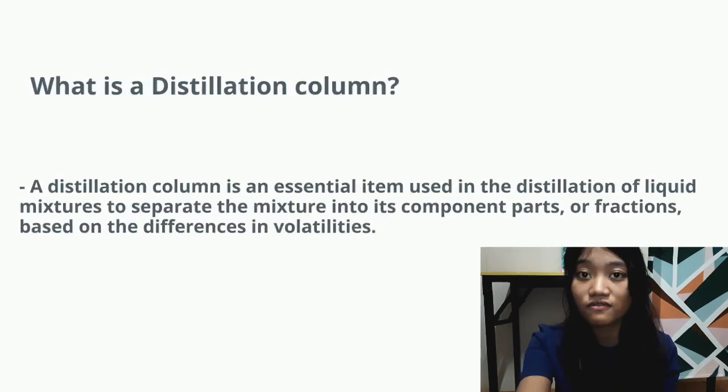The quality of the separation performed by a column can be judged from the purity of the top and bottom product streams. So the specification of the impurity levels in the top and bottom streams and the degree of recovery of pure products set the criteria for a successful operation of a distillation column.